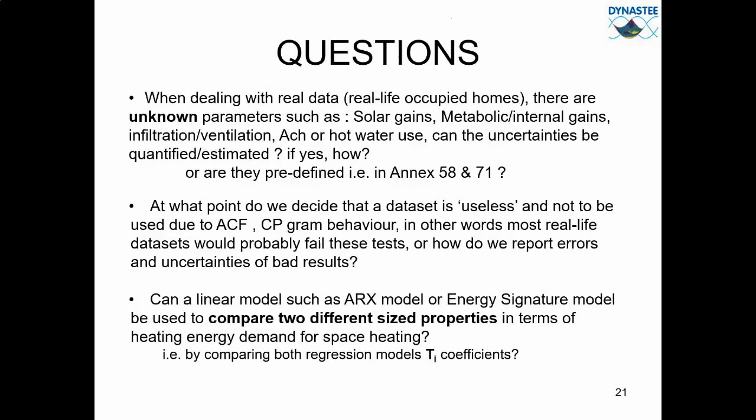Because probably if you are working in winter in very cloudy periods and it's cold and rainy, solar gains will be really small. If those periods that you are analyzing are also very cold, probably the metabolic heat gains would be very small compared with the heat gains of the heating system, which can be measured very accurately. So you have to try to analyze the building.